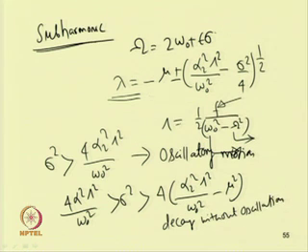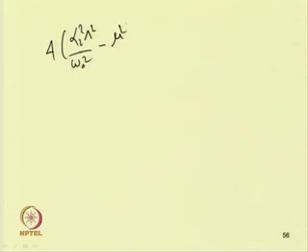So, the last one, when we will get this positive root, that means, if we consider the condition 4 alpha 2 square lambda square by omega 0 square minus mu square greater than sigma square, one can observe that the system response will be unstable as the response will grow beyond some bound. But in actual case the system response cannot be unbounded. So, one has to perform the nonlinear analysis, or one can take additional terms to study the system response and stability of the system.